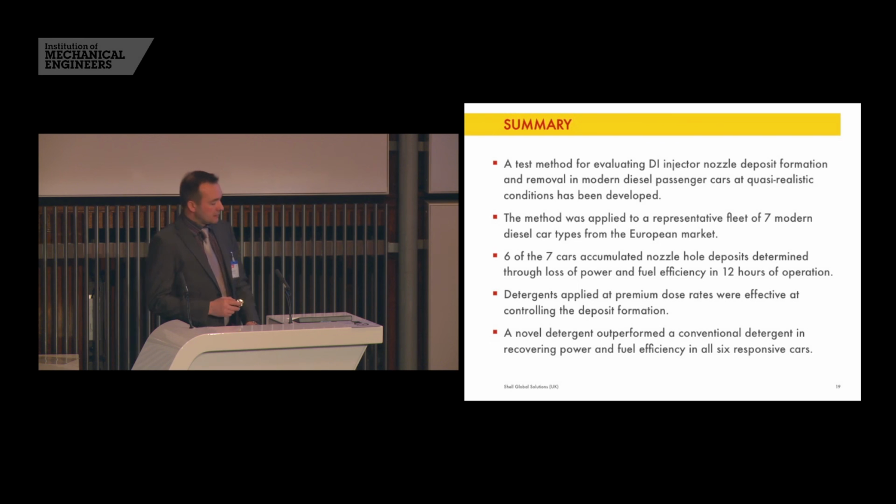So in summary, we've developed a test method for evaluating DI nozzle hole deposit formation and removal in modern diesel passenger cars at quasi-realistic conditions. And we've applied that method to a fleet of 7 representative vehicles from the European market. And 6 out of the 7 cars accumulated deposits, which was determined through loss of power and increase in fuel consumption.